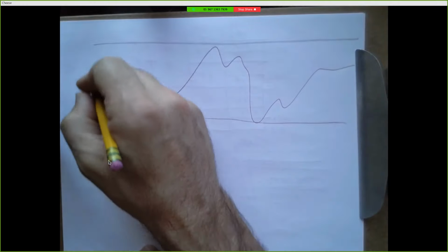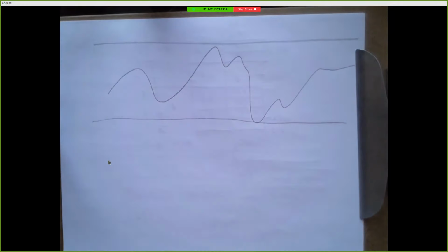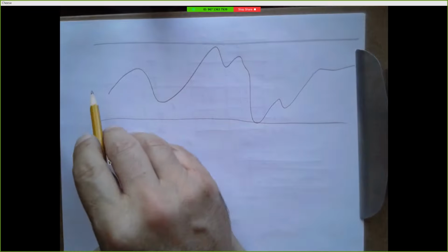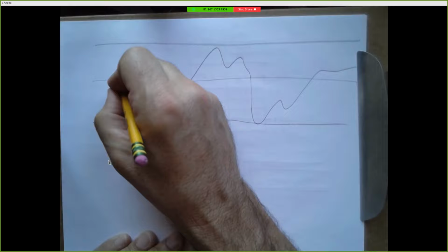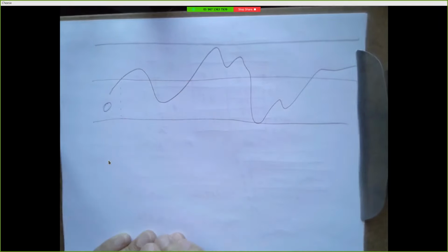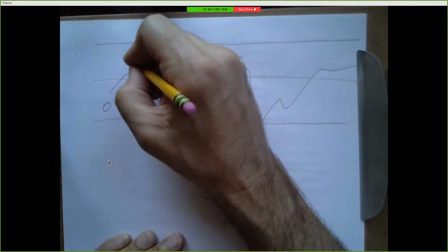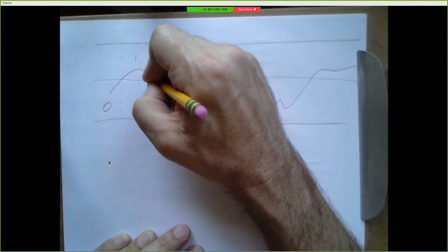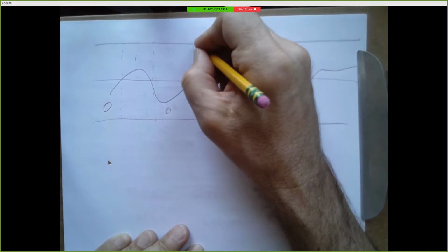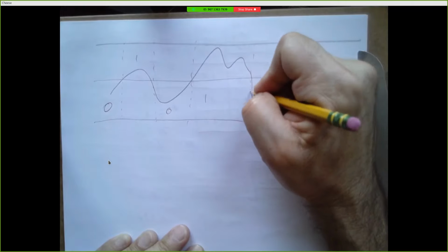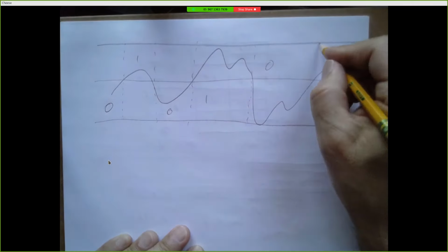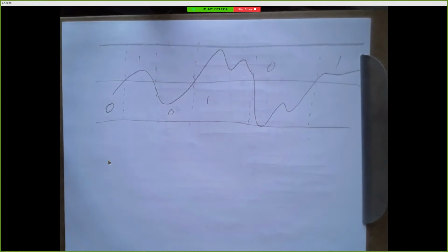And it's always somewhere between these two voltage levels. Well, if we do a 1-bit analog to digital conversion, what do we have? Over here, the signal will be considered a 0. Up here will be considered a 1 until you get to this point. Now it's a 0 until you get to here, and then it's a 1, and then when you get over here it's a 0, and then when you get over here it's a 1. Pretty crude, right?